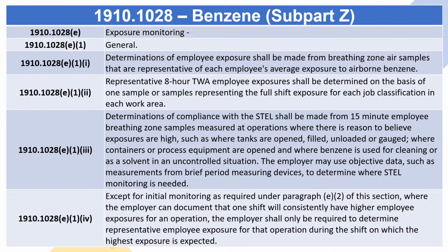Determinations of compliance with the STEL shall be made from 15-minute employee breathing zone samples measured at operations where there is reason to believe exposures are high, such as where tanks are opened, filled, unloaded, or gauged, where containers or process equipment are open, and where benzene is used for cleaning or as a solvent in an uncontrolled situation. The employer may use objective data, such as measurements from brief period measuring devices, to determine where STEL monitoring is needed. Except for initial monitoring as required under paragraph E2 of this section, where the employer can document that one shift will consistently have higher employee exposures for an operation, the employer shall only be required to determine representative employee exposure for that operation during the shift on which the highest exposure is expected.